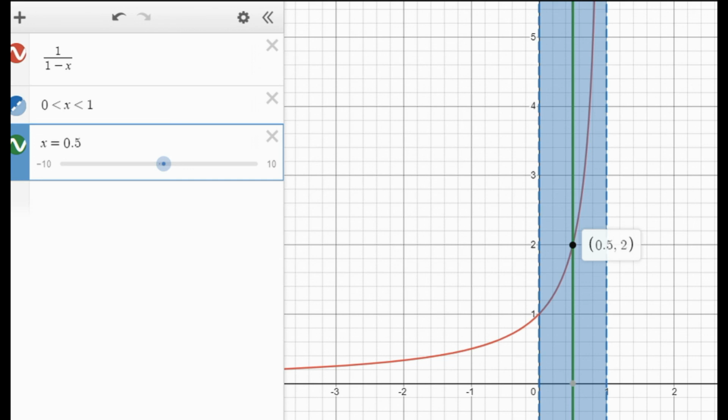So we have to stay within a reasonable region of duty cycle, about 0.4 to 0.6. We don't want a higher duty cycle than that. Once you start designing, you'll see how you need to match the inductor with the switching frequency to make sure that you end up where you want your output voltage to be.